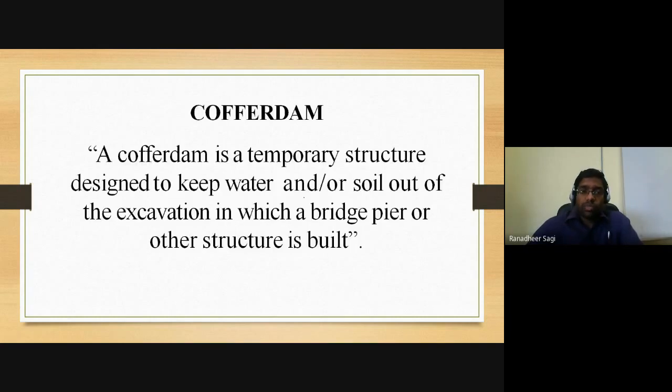So coming to what is meant by Cofferdam. Cofferdam is basically a kind of a temporary structure which is designed to keep water and or your soil out of that particular region in which you are required to take up the construction of any bridge pier or the caisson foundation. That's nothing but your deep foundation, in the purpose of construction of your deep foundation across your water bodies or in the water stagnated areas.